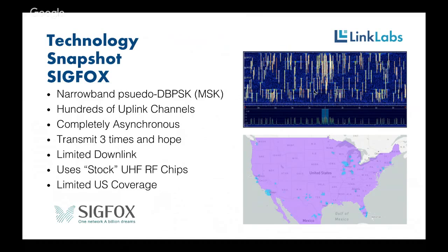And another nice thing about it is it uses stock, very inexpensive UHF RF chips that are available for $2 or so. It's completely asynchronous, meaning that the devices just wake up and send. There's very limited ability to send messages down to devices with any type of consistency. So it's mostly for meter reading and other low-cost, low-end, low-performance type applications.